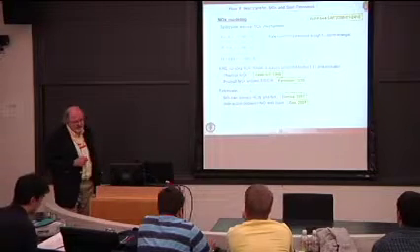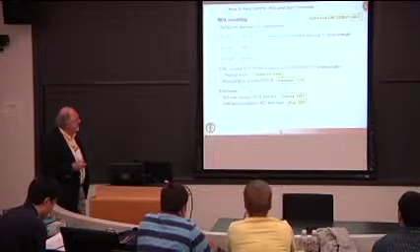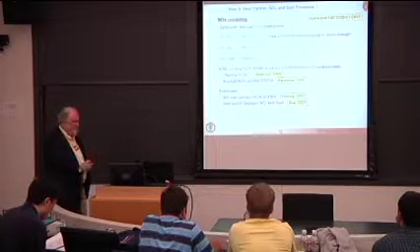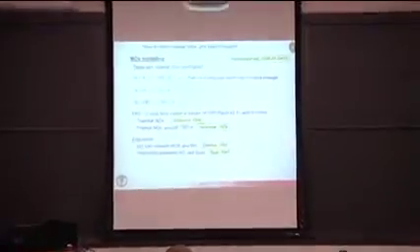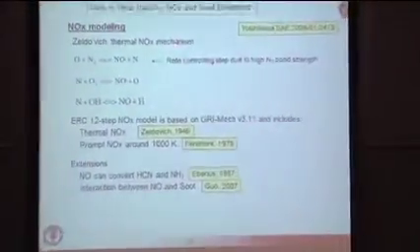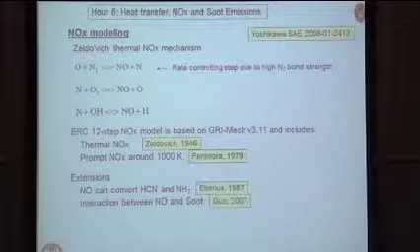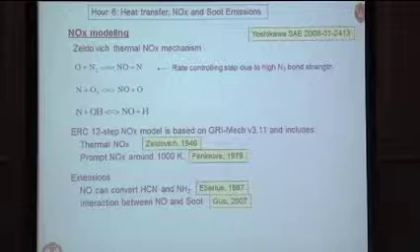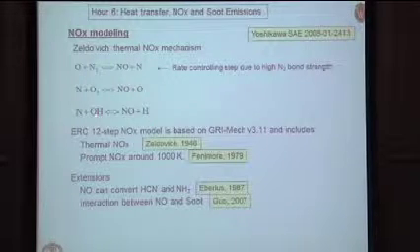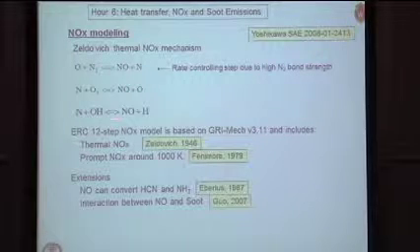Okay, so let's talk now about the kind of models that are used to model, for instance, NOx, and then hopefully we'll have some time to discuss particulate. The standard model is the Zeldovich NOx model, which I'm sure you're all familiar with. Basically, it's the initiation step because you have to break this N2 bond here. And then there's the so-called extended Zeldovich, which includes OH attacking nitrogen atoms to produce NO.